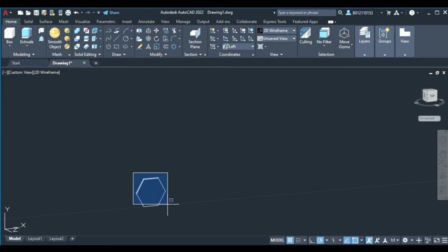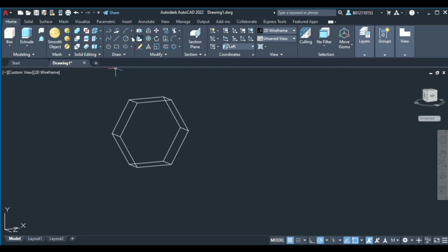And then we will have this shape, then we join all of the lines. Then we have this closed outline, we extrude it 0.1 centimeter, and then we have this thickness. And then there will be a sphere around the surface of this hexagon, a hemisphere. For that we need to find the center here, and then this center. Okay, make a line. Let's use the diameter of it. Make a circle with 0.2 diameter. Alright, and then trim just half of it. Right, and then it will be like this.